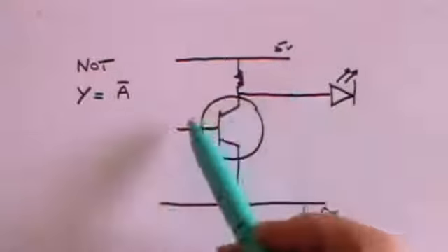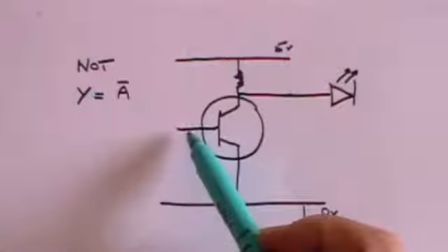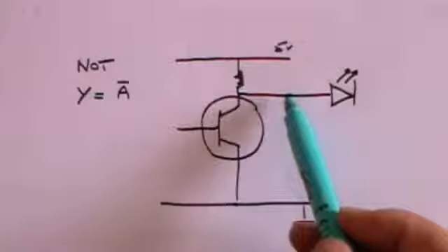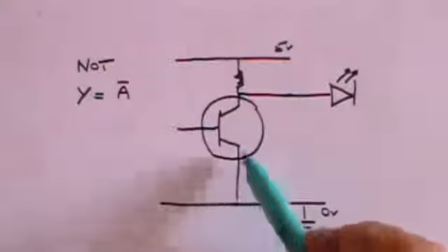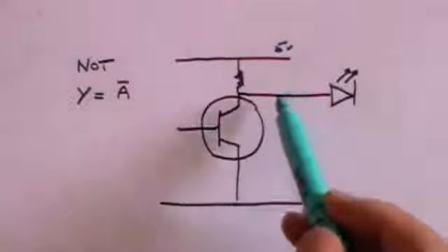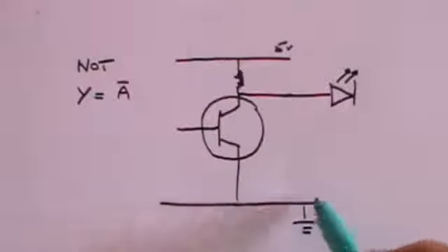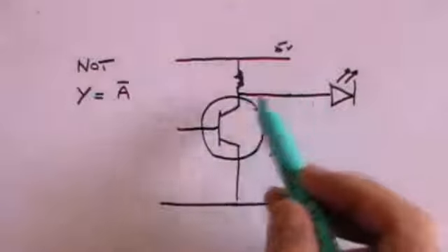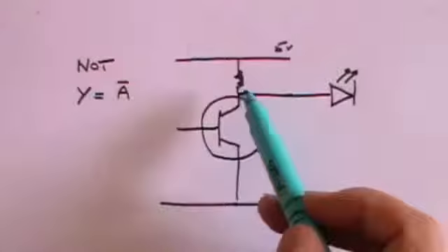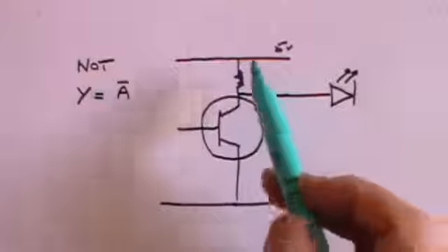And so you've now got a positive voltage on the base, the input, but now no voltage on the output because a current is flowing through here, and so essentially this and this are at the same potential. And that potential is 0. And so this potential is 0, and the whole 5 volts is dropped across the resistance here.